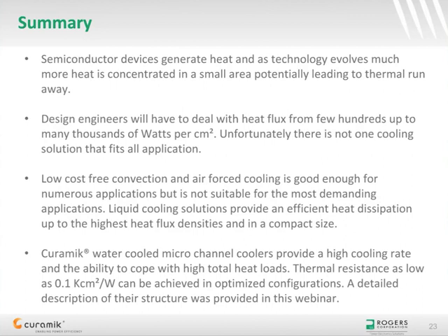Liquid and two-phase cooling solutions provide an efficient heat dissipation up to the highest heat flux densities and in a compact size. We have seen that curamik water-cooled microchannel coolers provide a high cooling rate and the ability to cope with high total heat loads. Thermal resistance as low as 0.1 Kelvin square centimeter per watt can be achieved in optimized configuration. A detailed description of their structure was provided in this webinar.